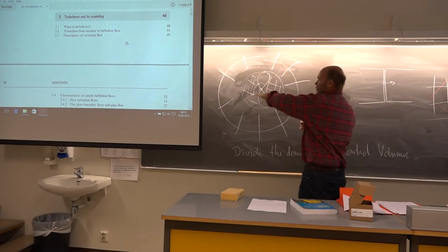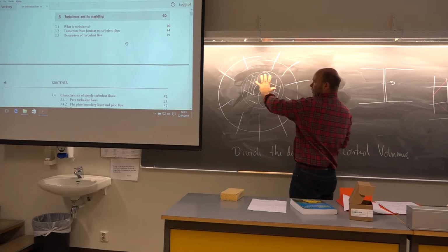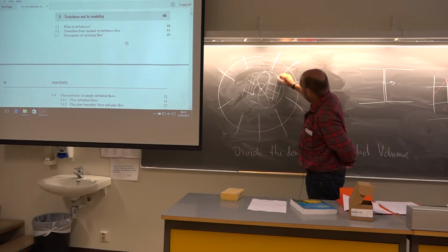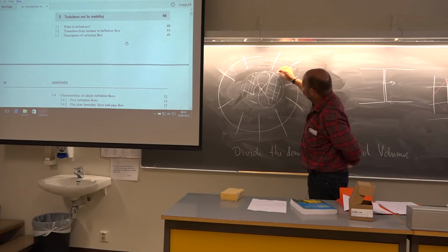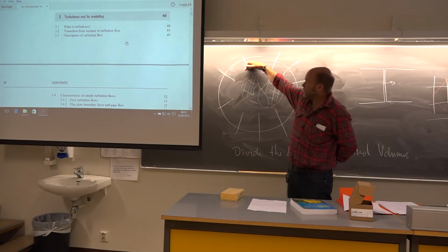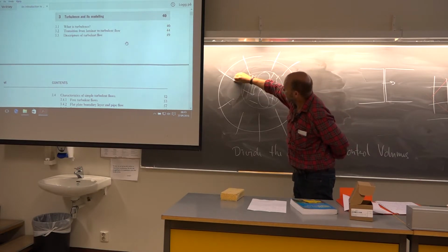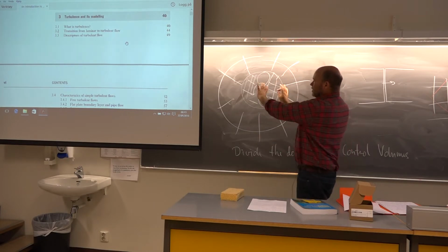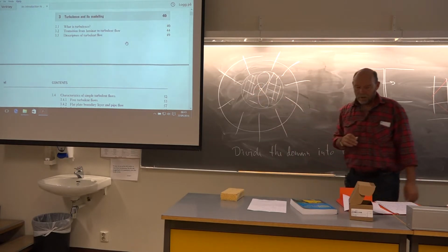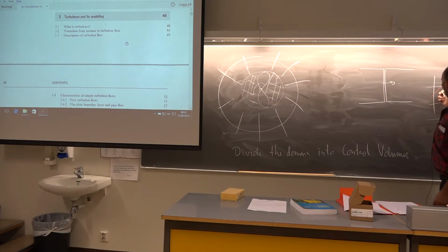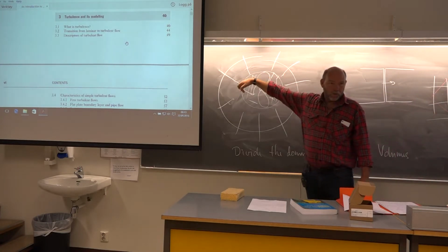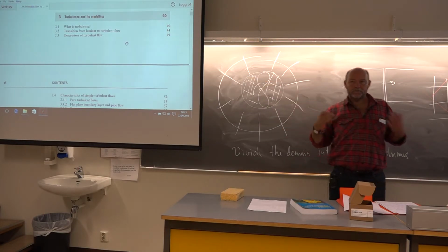So now the inner mesh will slide against your steady mesh, and these faces here will slide against the other volumes that don't move. Of course, a lot of interpolation here as well, and you have to remesh for every time step. But it is better than this overlap thing. So here they will still be face to face, although one mesh is moving.